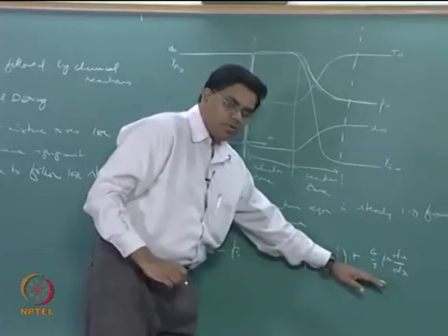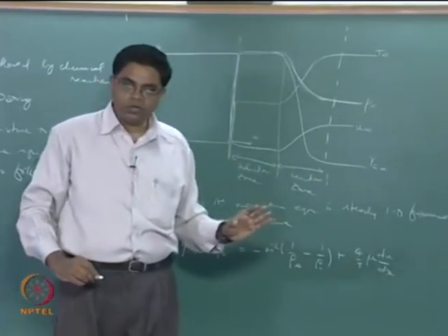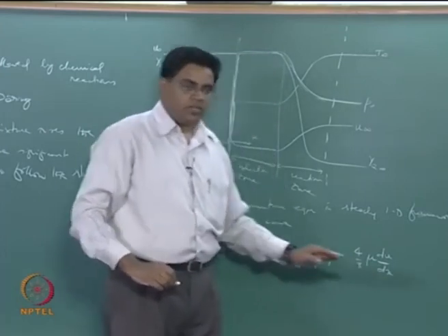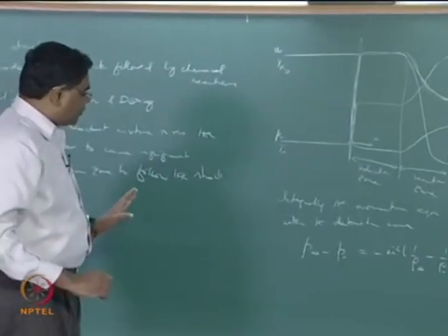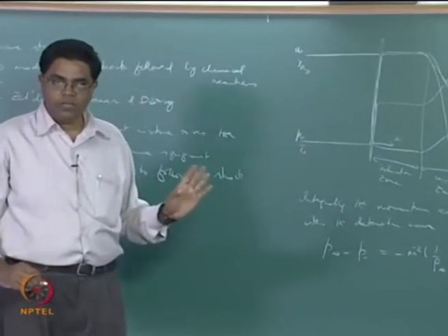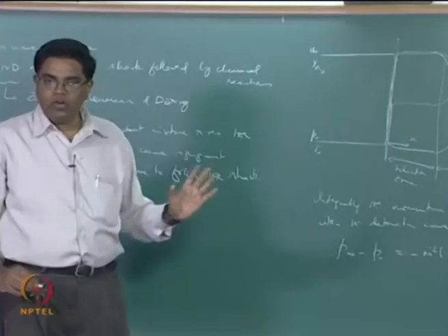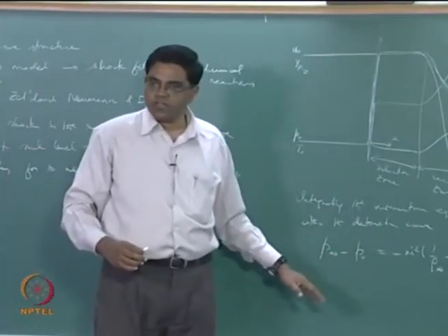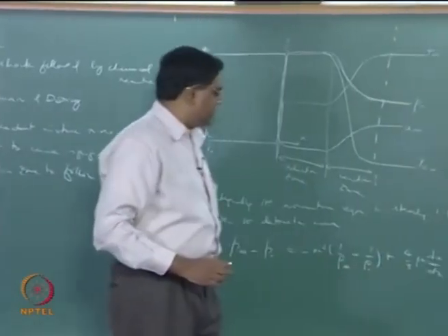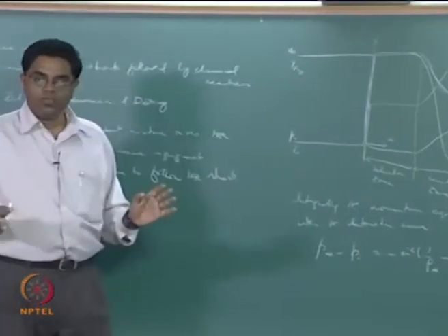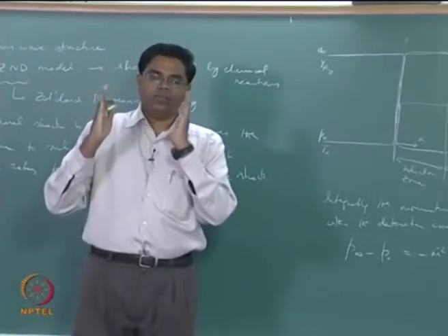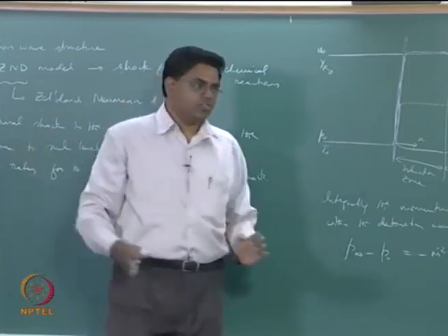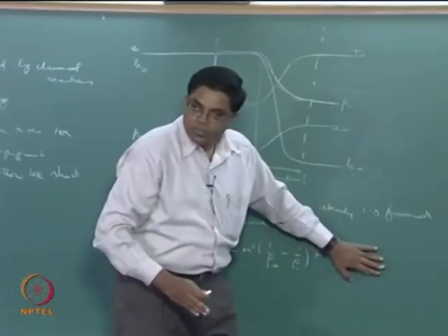When did we get this before? When we wanted to show that when you have very low Mach number, this will actually be of the order of Knudsen number times Mach number, and then the convective term will actually be of the order of gamma times Mach number squared. So under very low Mach number conditions for continuum flows with low Knudsen numbers, you got a pressure equal to constant approximately. That is when we tried to integrate it once. The next time we integrated it was in the Rankine-Hugoniot framework, but that is like saying all the gradients are within the wave. That means we are looking at outside the wave to get jump conditions, so you don't have the du by dx term at all.